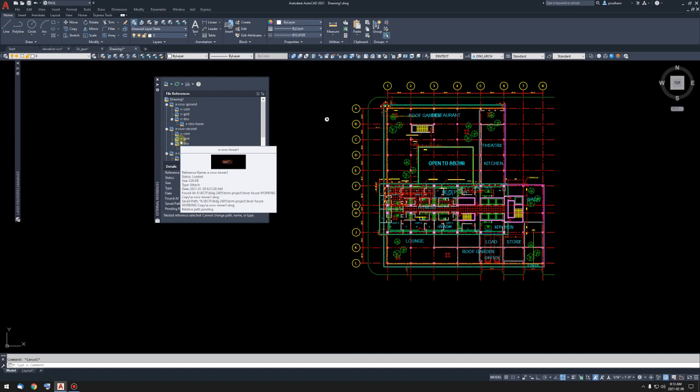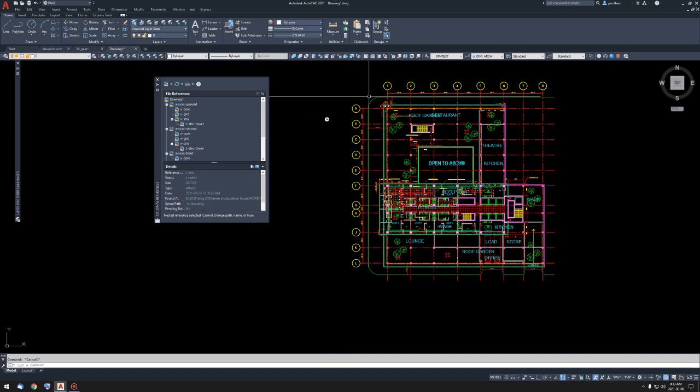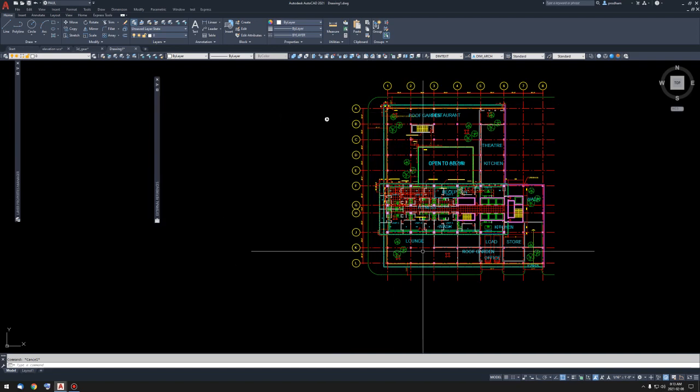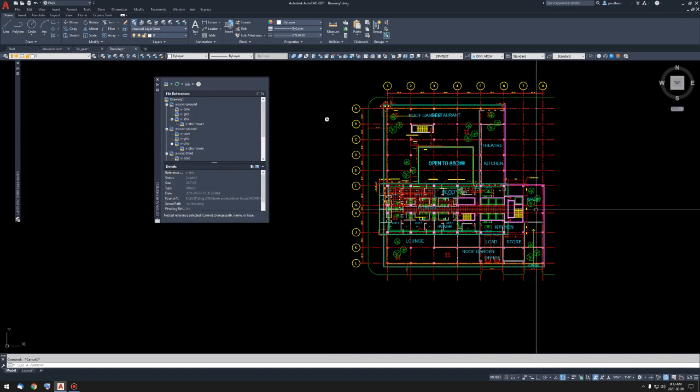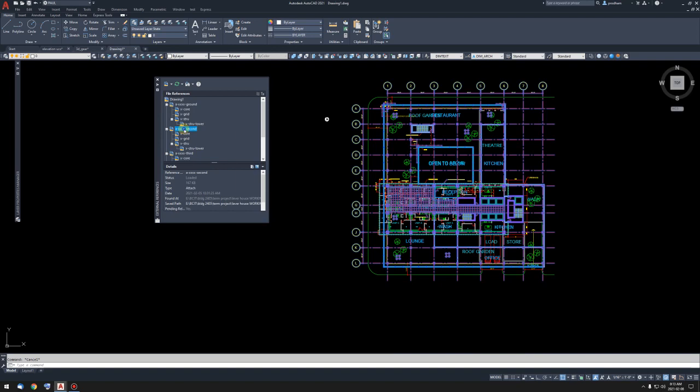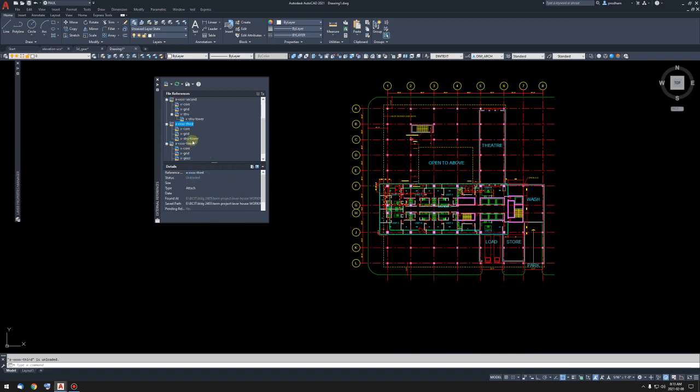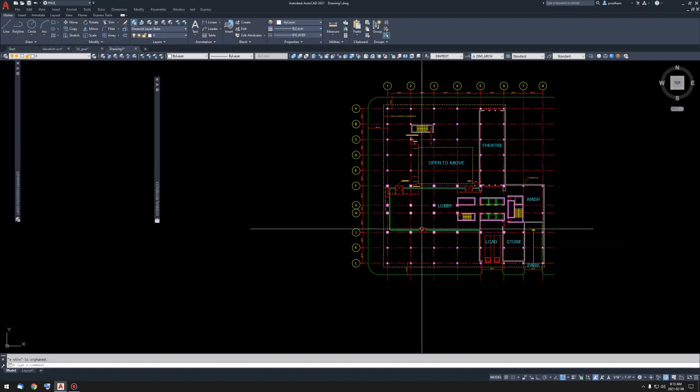And when we start to draw the elevations, again, we're going to be projecting lines from the plan to draw the elevation, but it's such a mess right now, right? It's pretty hard to see what we're looking at. What I want you to do is unload the levels that you're not currently working on. So let's say start with the ground floor, unload all the other ones. Now you can just focus on the ground floor.